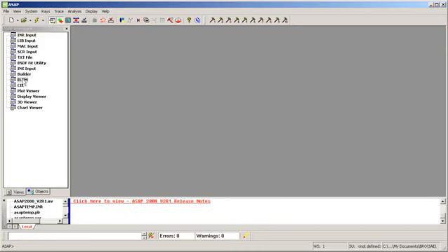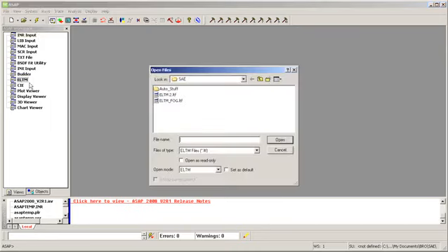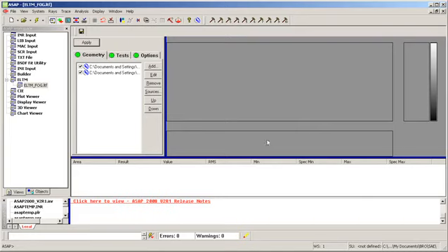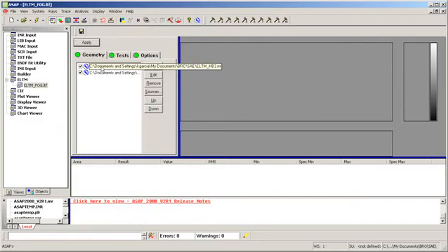We click on the ELTM button and we'll open up a predefined file, which has some of our fog lamp information in it. The exterior lighting test module screen is composed of several areas. First is an area to define your geometry. This geometry actually includes the source distribution and the reflector distribution.